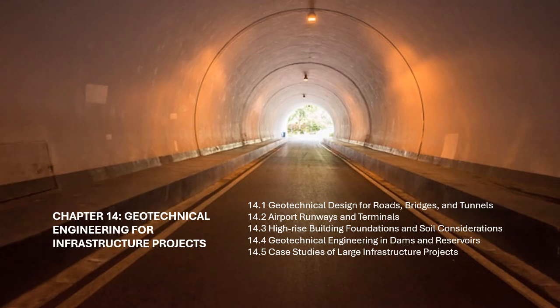Shear wave velocity test. This test assesses the stiffness of the soil and is essential for determining the soil's response to dynamic loads. Shear wave velocity is particularly important in earthquake engineering and for evaluating seismic risks.